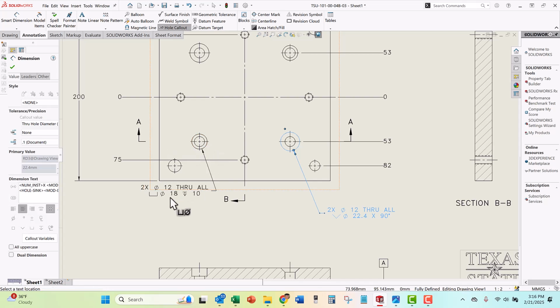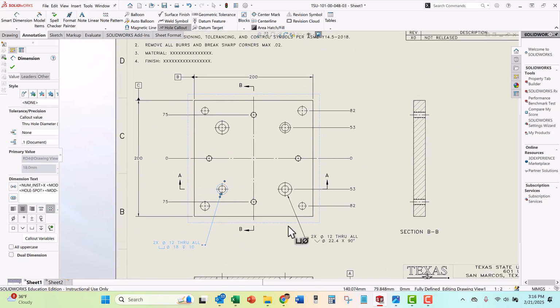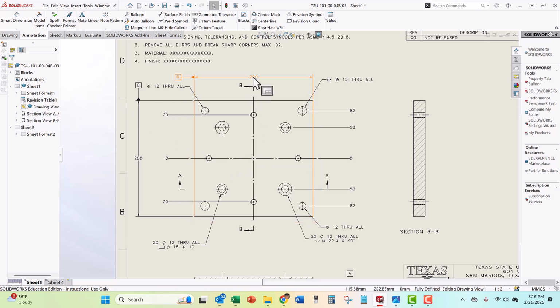Here's the counterbore. Same thing. I got the through hole defined. There's a counterbore diameter, and there's the depth of the counterbore. And we'll get this. This looks like the screw clearance hole. That's for the hex bolts. And I need 2 call outs. I need a different call out for this pin. One of those is going to be a press fit, FN fit, and the other one's going to be an LC fit for a clearance hole fit. So I need 2 call outs for that.